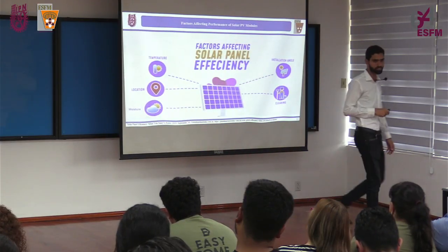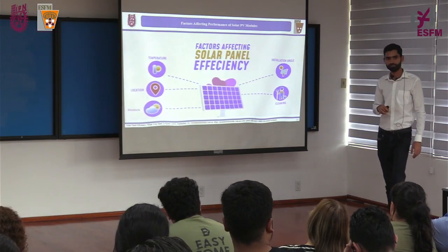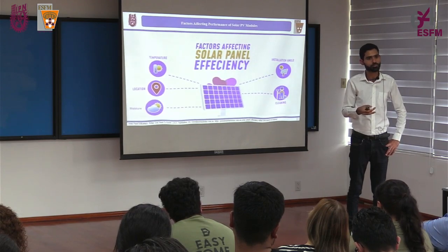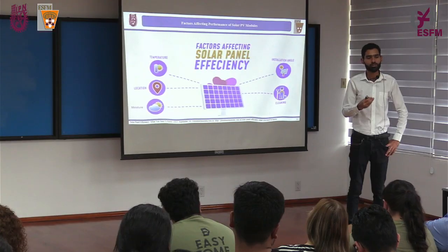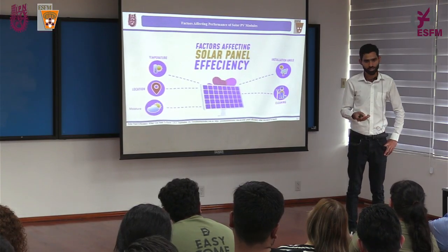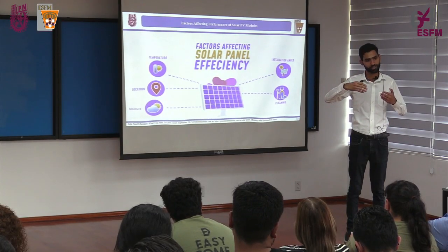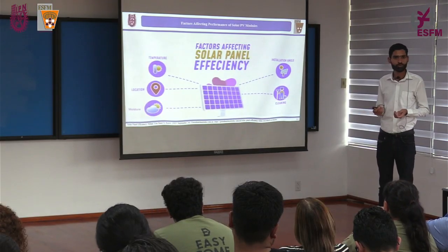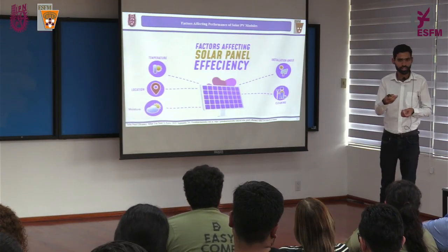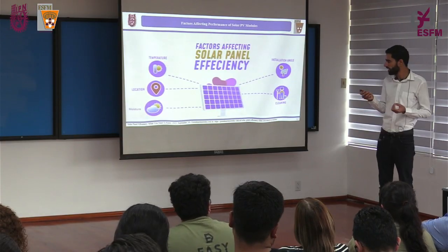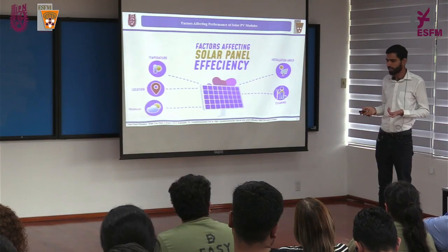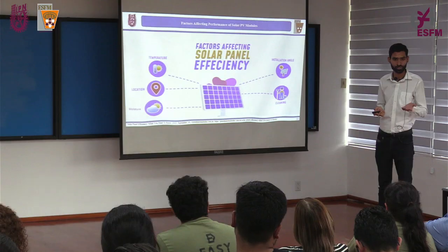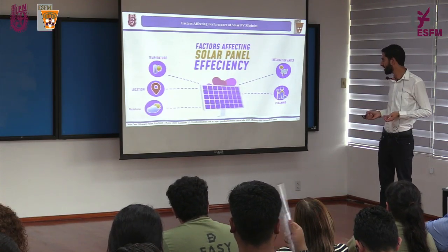Another thing which is very important is moisture. As I already told you, in perovskite we normally use lead-based material. And why does perovskite material have low stability and low lifetime? Because lead with moisture creates lead oxide, which diffuses out from the main material and reduces the output of the device as well. Also with moisture, the metal back contact, the electrodes we have, can corrode and the material can degrade, and once the material degrades, the main material will be lost, and we will not have enough material to convert solar energy into electrical energy.